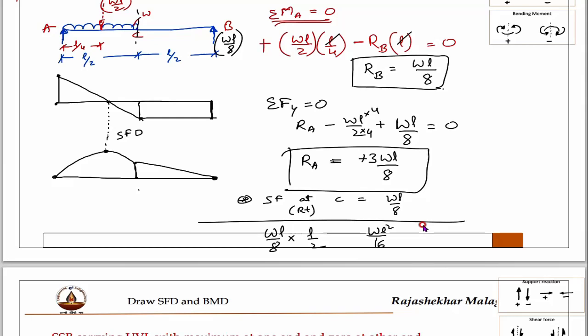Oh, sorry, maximum bending moment diagram. Now you can find this distance, calling this as x, and this one is L by 2 minus x. Then by using similar triangles method you can find the x value. After finding x value, you can even determine bending moment here.